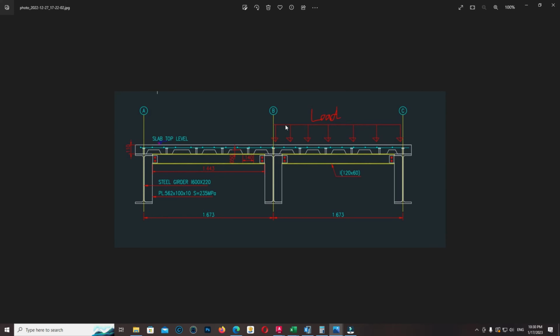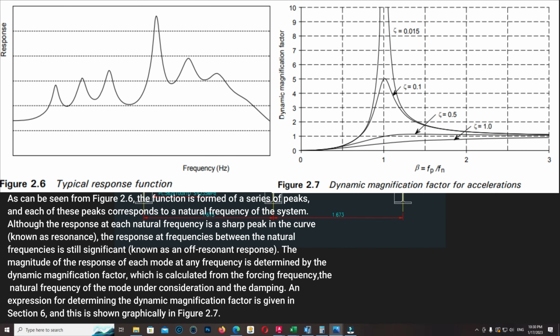So in the steel bridge we should apply different load patterns. Sometimes a load pattern maximum on the left side, or on the right side, or in the middle of the bridge can produce different effects on the bridge. It is very simple. You can apply the moving load.